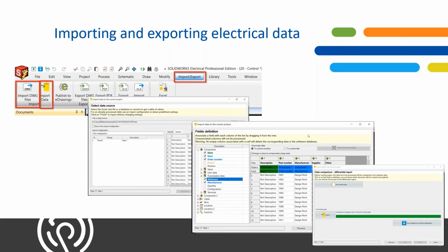If you have those in a DWG format, you can take either AutoCAD, DXF or DWG formats, import those in electrical schematics and reuse that information so you're not redrawing something that you previously drew before. All you would need to do to turn it into a smart electrical component is import it, delete what you don't want, and save that symbol to a particular name and to a particular location.